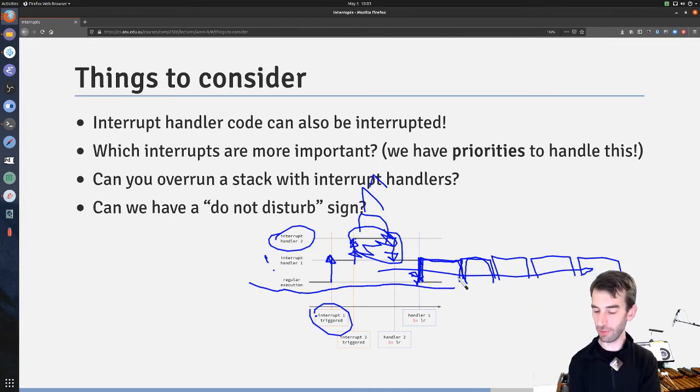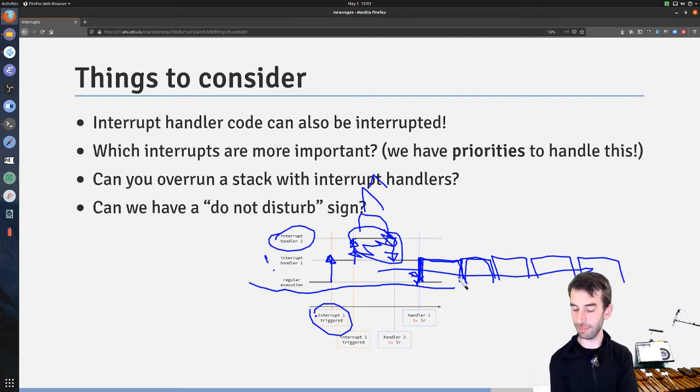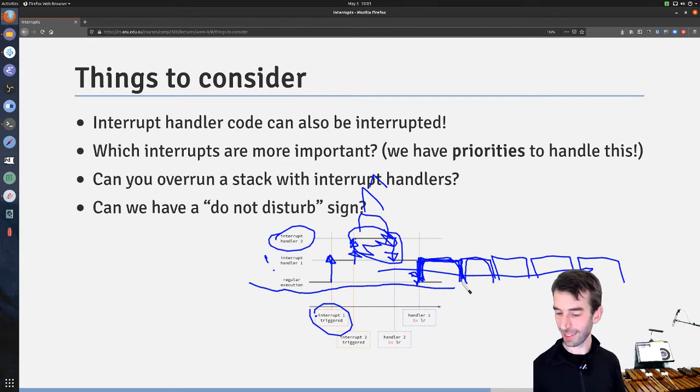Is there a limit to the queue of interrupts? I don't think it's going to work exactly that way, because it can't queue them up. It's just not going to fire until you handle it. So potentially if you took too long, then your second interrupt might have actually disappeared by the time you get to it. We'll have to work on understanding that one a bit more in depth. Maybe on the next lecture this week, I'll have a good answer about that one.